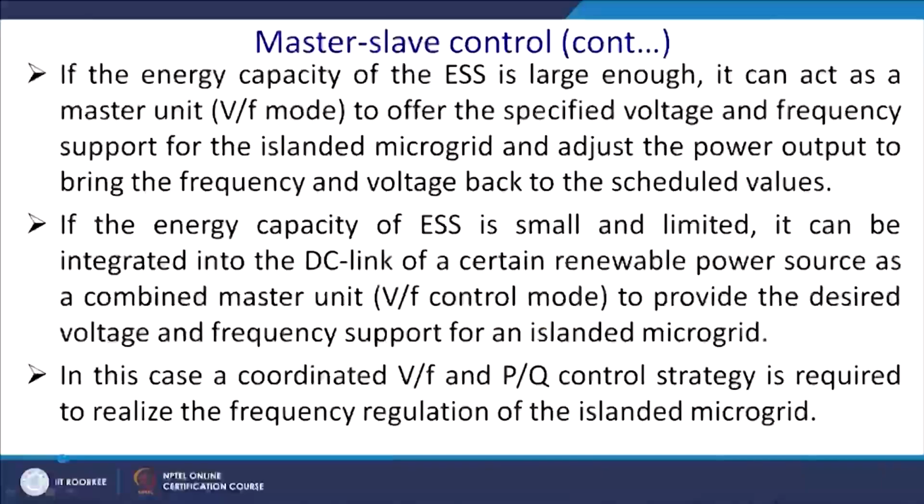Now, if the energy capacity of ESS is large enough, but that comes with the cost, please keep in mind, it can be set as a master unit in the V/F mode to offer the specified voltage and frequency support for the islanding microgrid and adjust the power output to bring the frequency and voltage back to the scheduled values. So, that is something you have to keep in mind: if you want to make your storage element a master, the capacity of the storage element will be quite big.